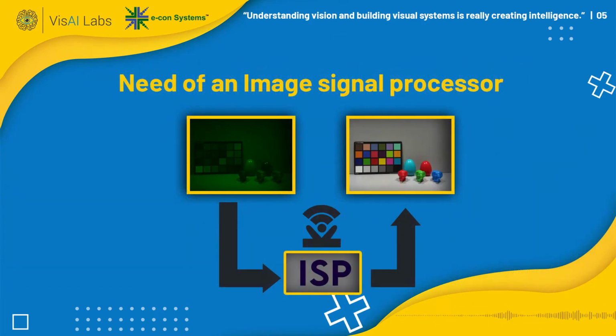What is the need of an ISP? What is an ISP first? ISP is a hardware or a software block which is responsible for most of the auto functions, the auto exposure, auto white balance, auto focus. All these things are taken care of by the image signal processor. The image on the left is what you get usually from the sensor. With the fine-tuned ISP, you will get something on the right. If it is not fine-tuned well enough for your sensor, then you may not get a very good image quality, regardless of what sensor you're going to use.